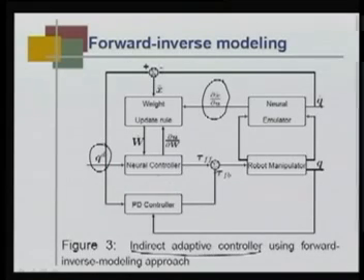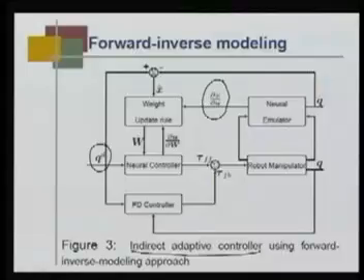And what is this neural network controller? This is again another radial basis function network. So, we have two radial basis function networks. One represents the neural emulator, another is the neural controller. In this radial basis function network, we fix the centers in their place in a specific domain, because we know what the various possible inputs to this controller will be, that is only QD, the desired trajectory. So, actually to this neural controller we have 3n inputs: n inputs from angular position, n inputs from angular velocity, and n inputs from angular acceleration.